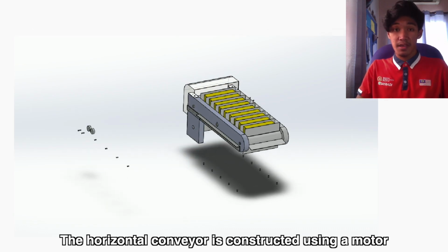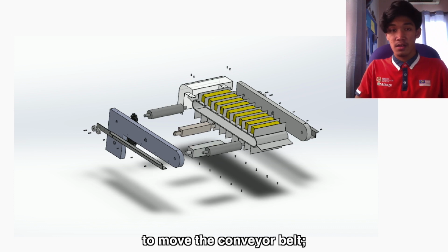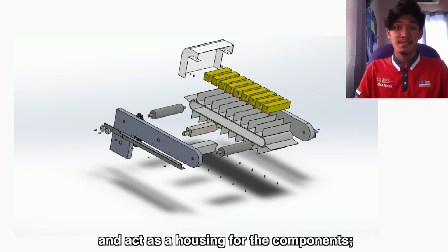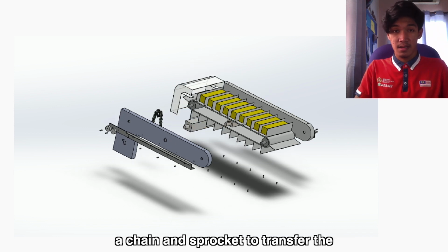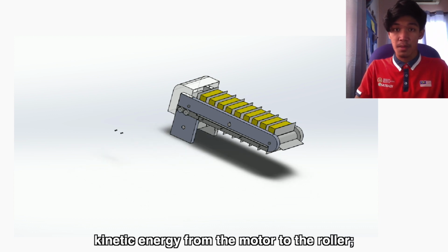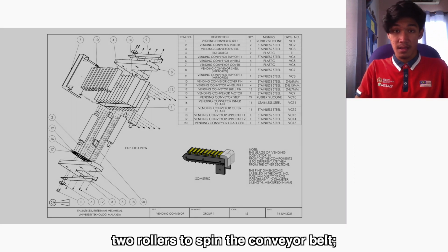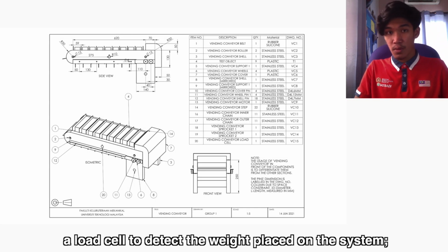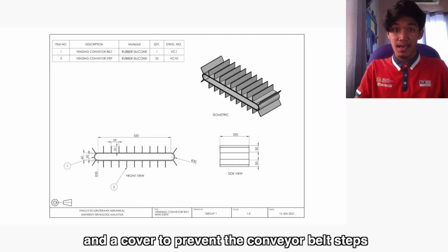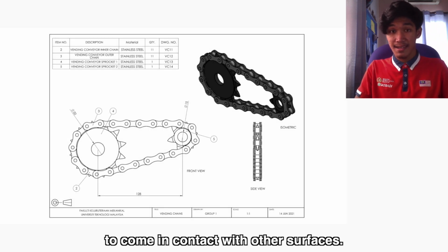The horizontal conveyor is constructed using a motor to move the conveyor belt, two shells to protect the side of the structure and act as a housing for the components, the chain and sprocket to transfer the kinetic energy from the motor to the roller, two rollers to spin the conveyor belt, a load cell to detect the weight placed on the system, a conveyor belt to place the items, and a cover to prevent the conveyor belt from coming in contact with other surfaces.